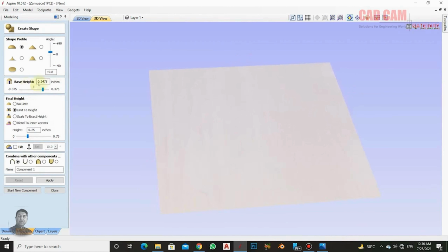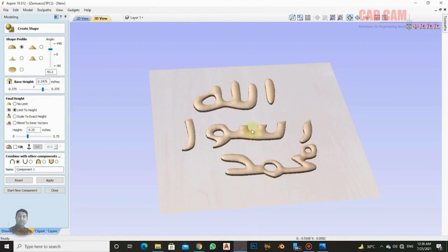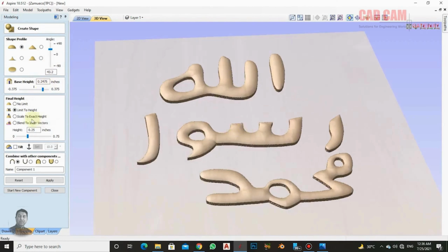I took its view, and here the very first thing we have is the curve profile. Turn on the curve profile and make sure to give it a little bit of degree. Here I've set the degree and it will immediately start tracing and creating it. Now, as soon as you change any value, the 3D effect will start to appear right away. Here I'll set a limit for its height.